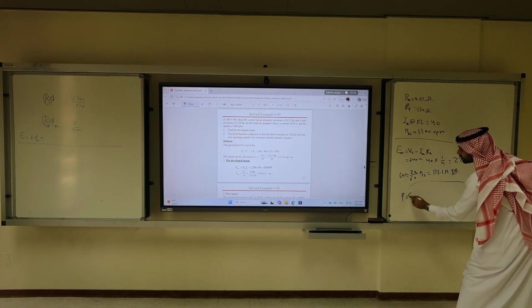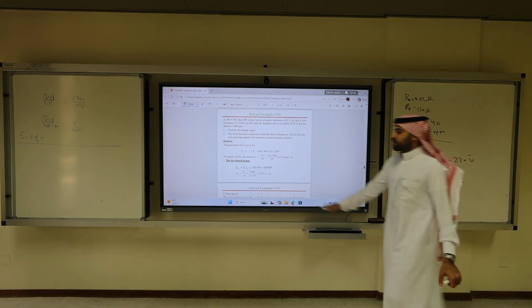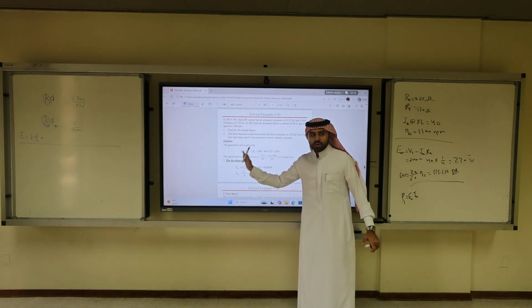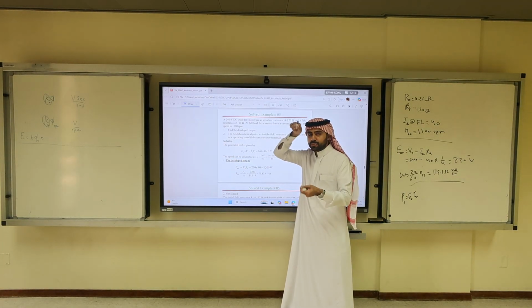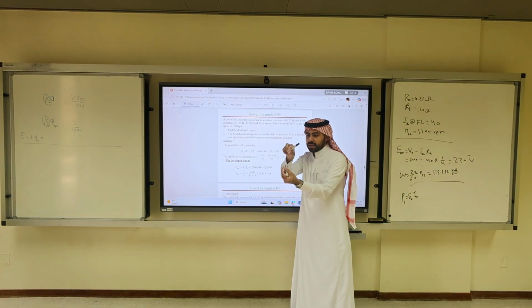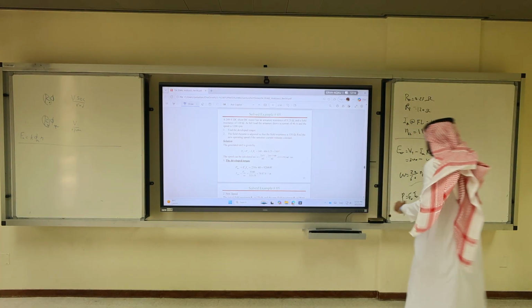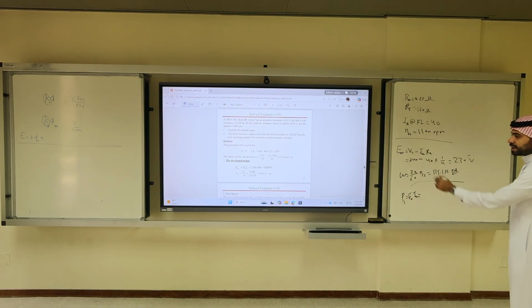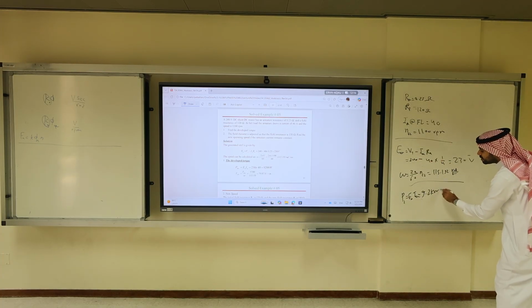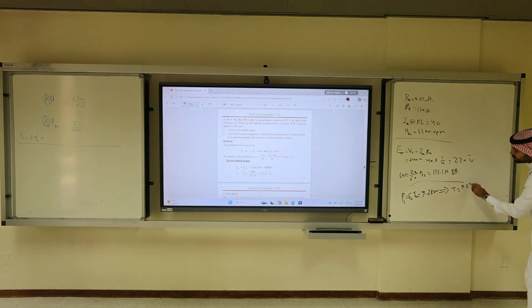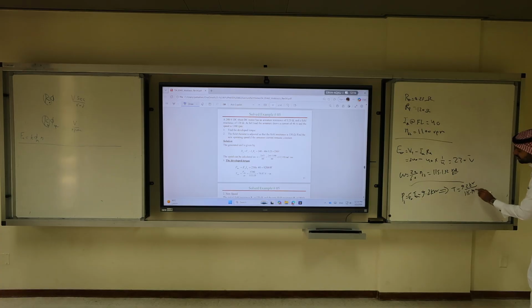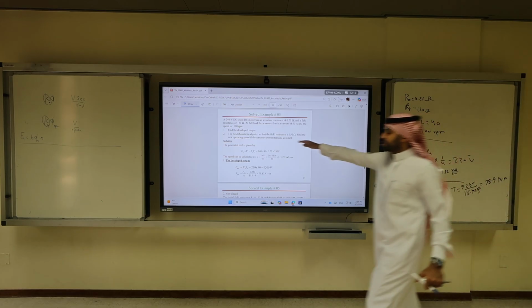So what is the developed torque? Get the power, EA times IA. This is the developed power, P or PD or PDEV, as long as you know what quantity you're talking about. It's not the input power, it is the power across the brushes of the motor, the armature. You will calculate it to be 9.2 kilowatts. So what's the torque? 9.2 kilowatts divided by 115.192 radians per second, and you should get the torque to be, I don't know, 79.9. Okay? So now this is from EE360.